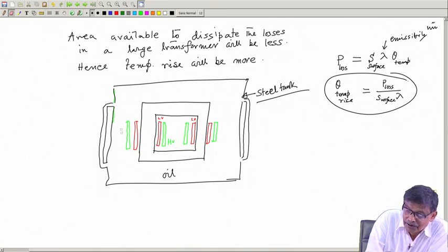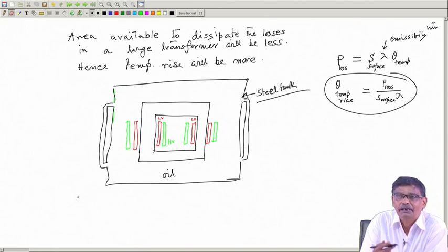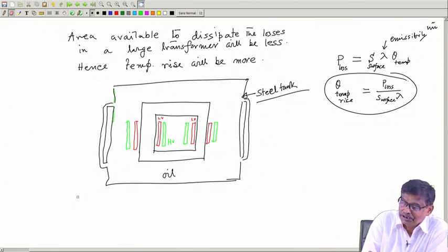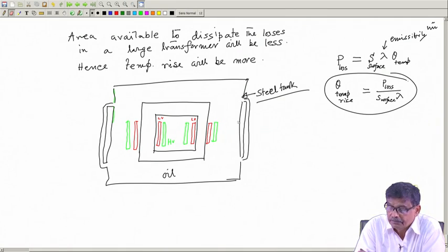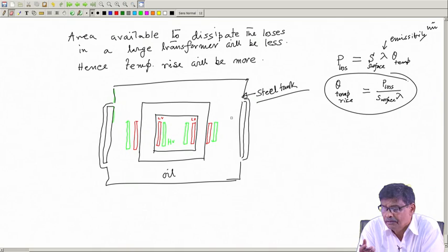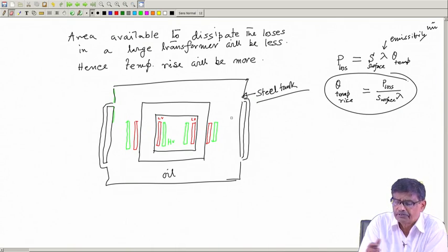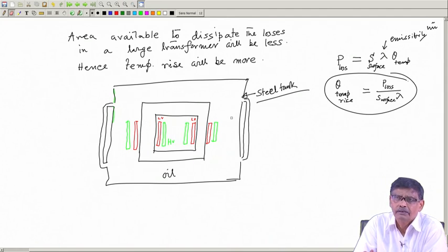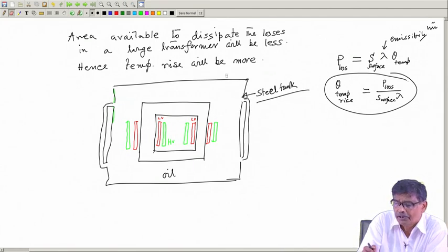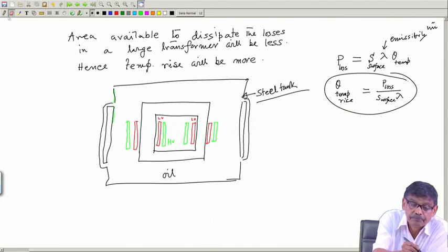So, oil will go up and it will have also natural convective currents, it will improve the cooling. So, heat will be coming to the cooling tubes. Mind you, it is not only one, it is just one I am seeing. Behind this, along all the surfaces you can connect. On the top surface and bottom surface, of course, no heat is assumed to be dissipated, because so many fittings will be there on the top. So, these are cooling tubes.